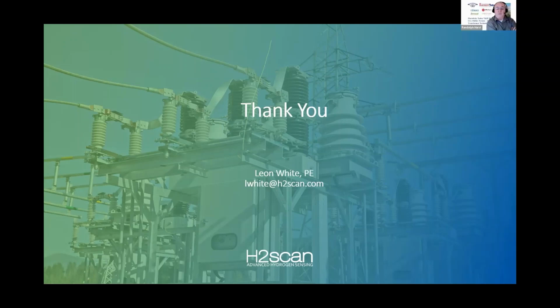Can single gas monitors be used on all size transformers, even to supplement multi-gas monitors on large transformers? Absolutely. It's interesting that hydrogen monitors are getting smaller and smaller today, to the point where they can pretty much monitor any fluid-filled transformer. Whether it's a 1,000 MVA large transmission transformer or even an oil-filled PT or CT, there are monitoring solutions available for those today.